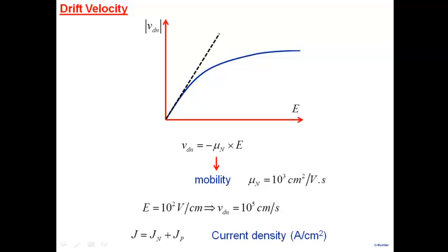When you apply a magnetic field and an electron is moving, the magnetic field deflects it in a particular direction. Now, when I do a Hall effect measurement, I find electrons deflect in one direction, and the holes behave entirely like a positively charged particle. The holes will deflect in the other direction. In fact, we know that underlying deep physics, yes, there is a missing electron. But for all practical purposes, think of it as a real positively charged particle with a certain mass, so it behaves exactly like an electron, but with a positive charge.